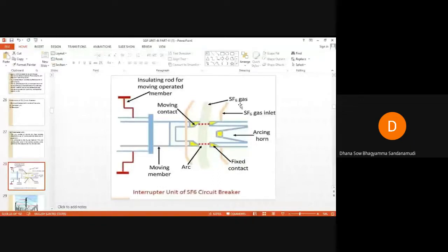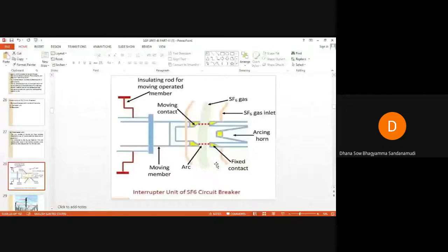So this unit consists of low and high pressure chambers, with a low pressure alarm along with a warning switch. When the pressure of the gas is very low, the dielectric strength of the gas decreases and the arc quenching ability of the breaker is endangered. Then the warning alarm will sound to warn the engineer who is monitoring the operation of this circuit breaker.